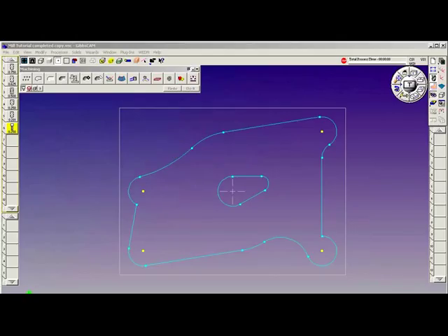We're going to apply these 6 tools to the geometry. I'm going to drill an entry hole for my end mill to begin the machining. In order to do this, I'm going to do a multi-tool process. I'm going to use a drill to do an entry hole, a rough end mill and a finish end mill, all grouped together as a process. Select the geometry and do it.